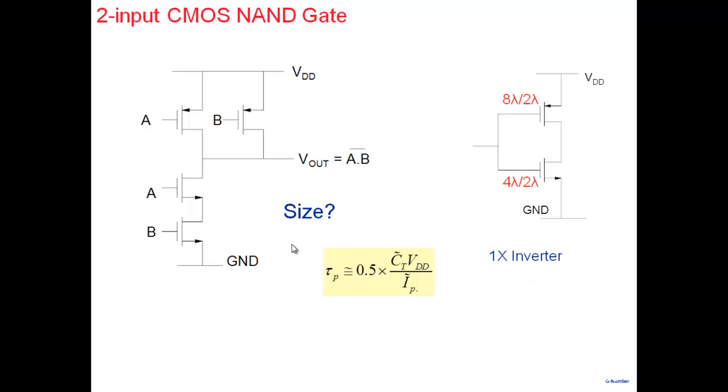what we would like to do is size this particular NAND gate such that under worst case condition, the strength of this particular gate is the same as the strength of this gate. Now strength in what? Strength we are talking about is the ability to charge up a capacitance, a load capacitance here. So we are talking about the strength of, let's say, the pull down network. Pull down network is here.